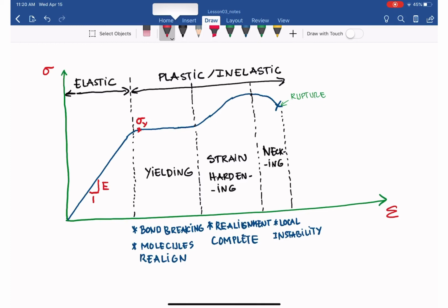So that is the point with the normal stress sigma yield where the material starts yielding. And the point just before it, in the elastic region, with sigma very close to sigma yield, we call sigma elastic, E or EL. If we apply stress up to sigma EL, it is still elastic behavior, and the original form can be returned if the stress is released to 0.